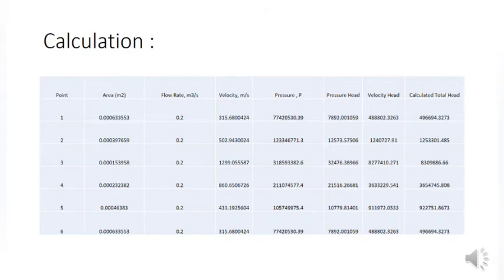We can see the constant value is the flow rate, Q, which has no change, because the volume and the time taken is the same in the data given. The others change because the area is different, because the diameter we got before is different on the venturi pipe, which is the tapered duct.